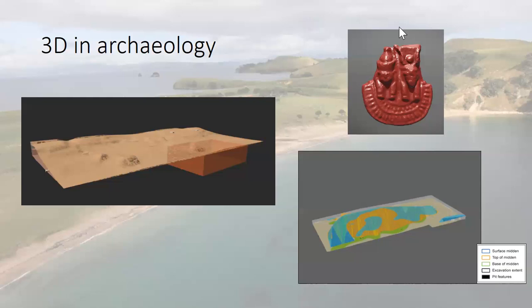And today I'm going to compare three methods of excavation recording, the data from which are used to create volumes of the excavated deposits. So the methods in question are photogrammetry, LiDAR using the Simultaneous Localization and Mapping algorithm called SLAM, very catchy title, and total station recording.